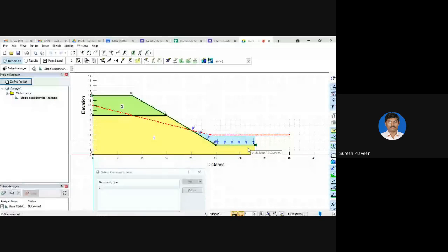Here we have to remember, since we introduced a water table in the embankment, there is no need to give the unit weight or the pressure due to the water, or hydrostatic pressure, because it is automatically induced in the analysis, right? So there is no need to assign the pressure of water or hydrostatic pressures again, because it is already induced automatically in the analysis.